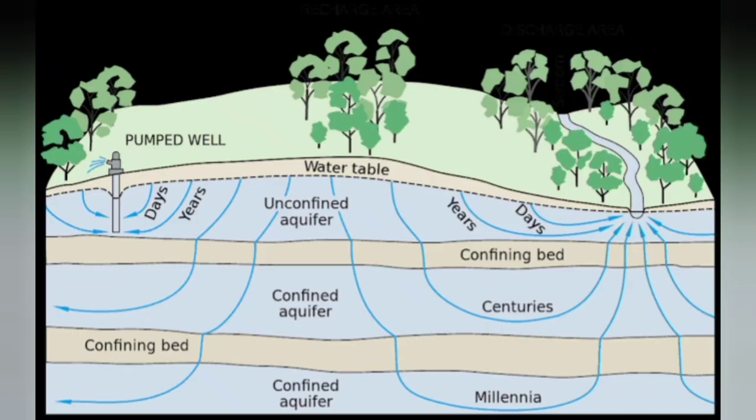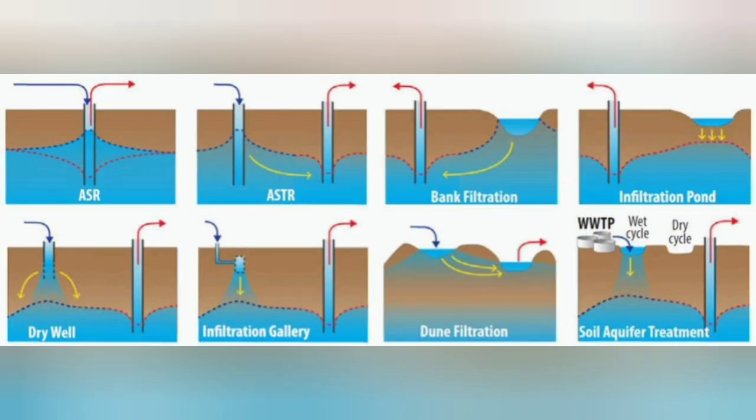First, near the surface, the interstices of soil may be filled up and a layer of mud may be deposited on the surface. On the other hand, suspended particles may penetrate deeper into the soil and accumulate there. So, methods to minimize the clogging effect by suspended matter can again be classified into different groups.